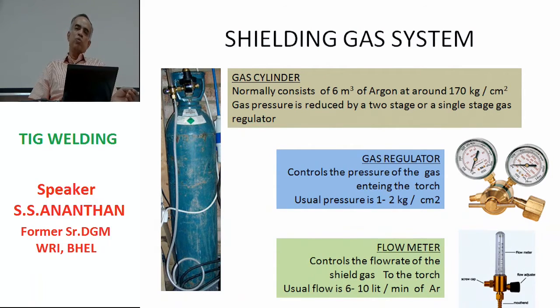Or when one goes for medical level tubing used in medical, biological, pharmaceutical applications, one goes for ultra high pure argon, which is 99.9995% purity. So these applications call for very high quality in welding without any oxide present.